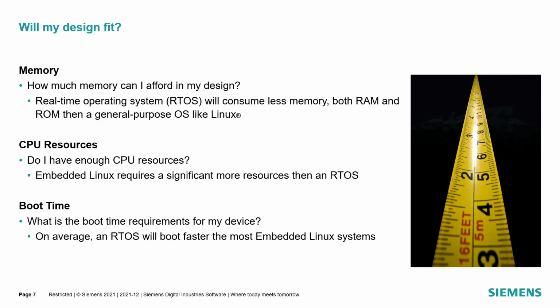There are other factors when you're talking about environments. What resources do I have available? Do I not have a lot of memory? Do I need a small RTOS to fit in here? Or do I have plenty of memory, so I'm not as concerned with the size of the operating system? Same with CPU resources. Do I have a lot or a little? That'll help guide you in which way best fits for you. And then also boot time. Do I need some really quick boot up? Do I have a certain requirement that on reset it has to be booted up within a certain amount of time?